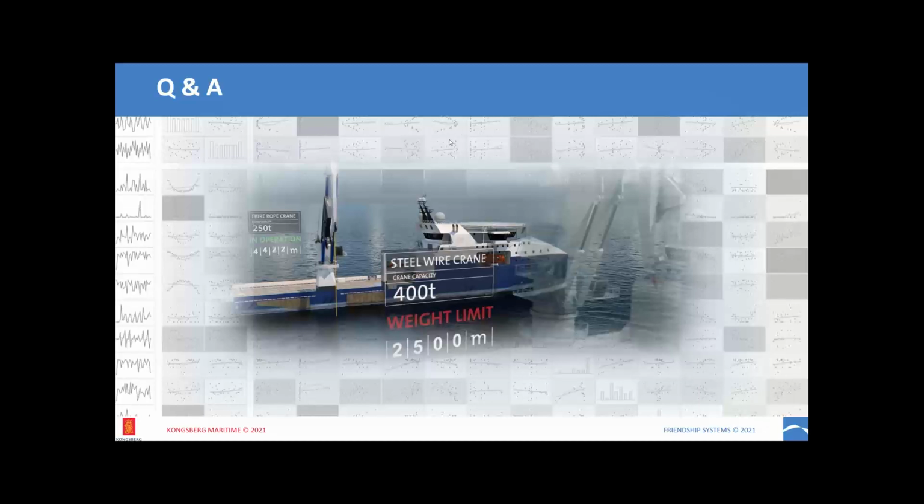Also, there was a question regarding the freeform deformation method, that someone did not find it in the software as it came from the website. That should be available there. The freeform deformation is basically a standard functionality, as well as the other morphing capabilities that Heinrich showed, and they should all be available in CAESES 5 in the model workspace. In the CAD tab, you have a menu for morphing, and you should find this functionality there.